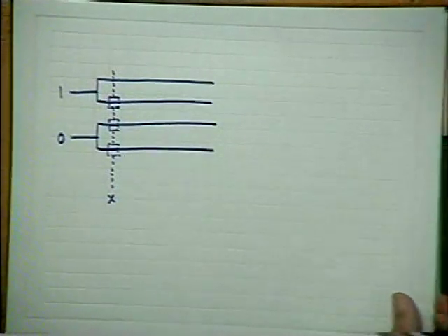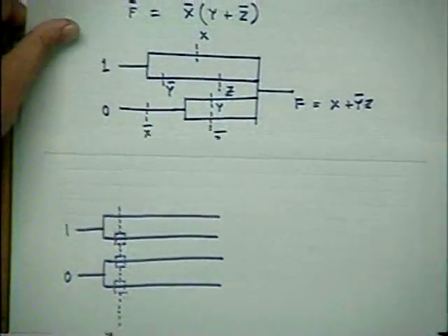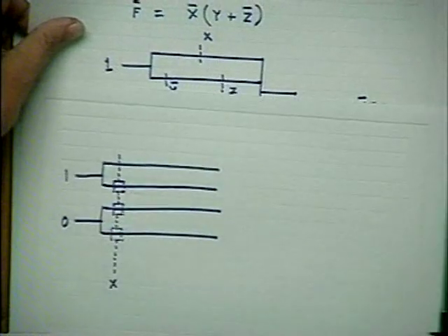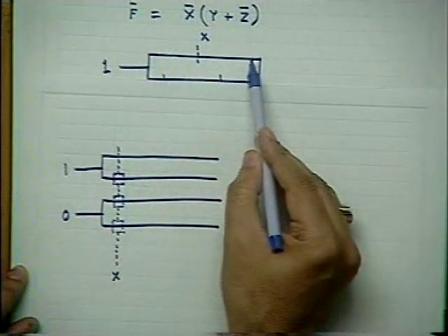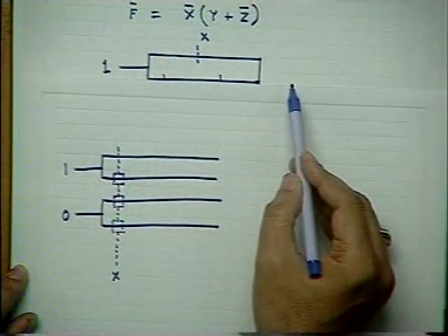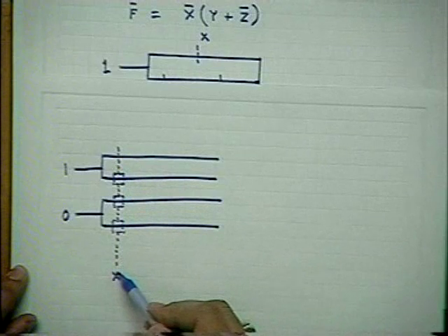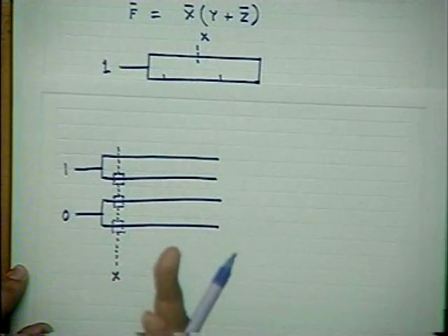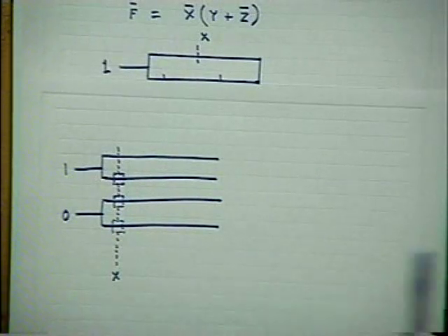Just see what I have done. I have to connect X in one branch, and that I have put. So this is an X, this is the polyline which carries the signal X. And these blocks are drawn because of the limitation of the stick diagram approach. I said that whenever in a stick diagram poly intersects diffusion, there is a transistor.